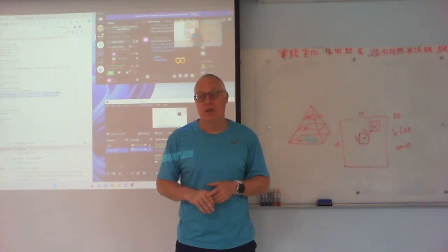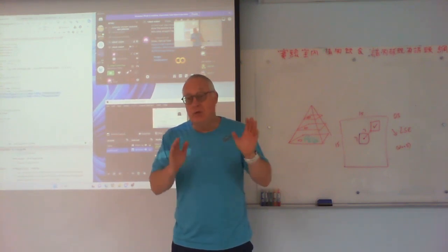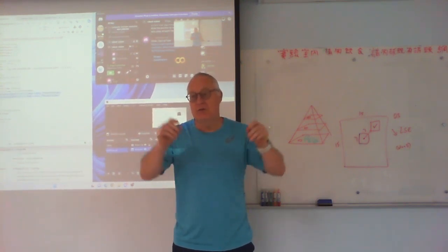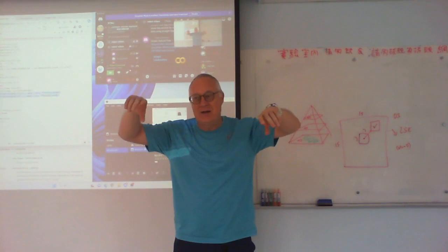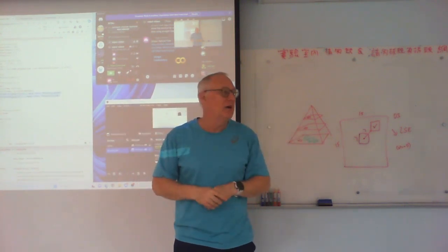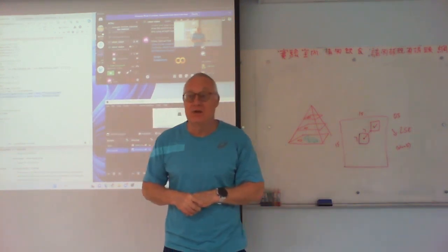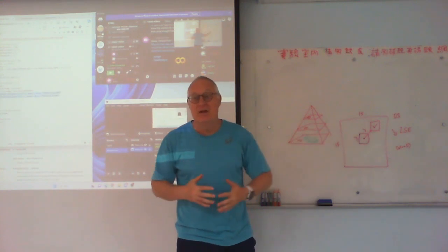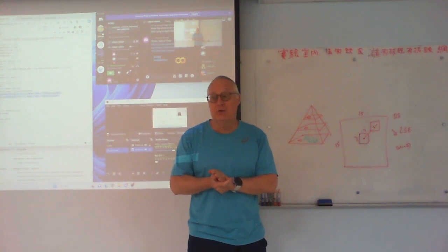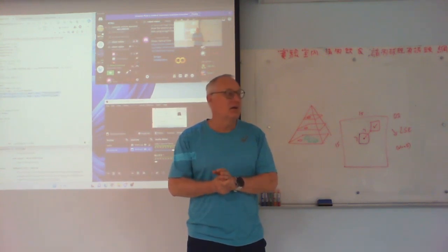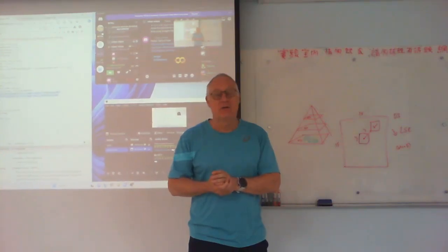Now, those feature points, you want to keep the old ones, because the old ones give you some very strong indication. If they're all moving in straight lines, their dy, dx all matches to the movement of the robot, then they're very good points to track, right? You've been very successful tracking them through the last n frames, so you don't want to throw them away and just start with a completely new set of feature points. On the other hand, you do lose points, so eventually you want to add new points to it.